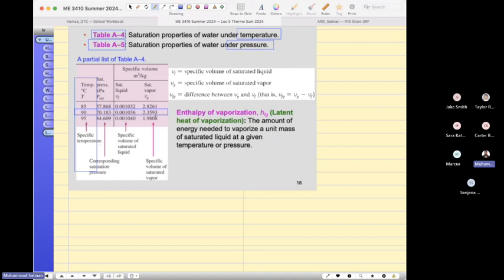As you can see, this is higher than this one, obviously. So this is VG, this is specific volume at the liquid line, and this is temperature. So this temperature is the saturation temperature. The latent heat is the heat between the liquid line and the dry vapor line. This is latent heat. The width of this line keeps on decreasing as we go towards the critical point. The critical point itself has sufficient energy that at that pressure and temperature, the liquid suddenly vaporizes.